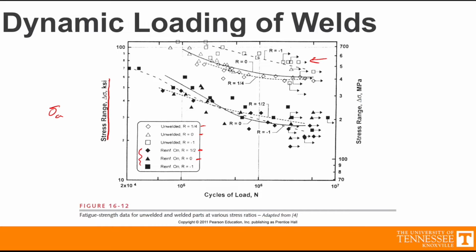One final thing to note about these SN curves and how dynamic loading works in welds is that we don't actually need to worry about correction factors for finding the fatigue strength in welds. And this is because the test data that was collected, so all of the fatigue strengths that are found for materials, have all been found via experimental methods. And so normally when we test an unwelded material, we have a very nice polished little dog bone sample that gets tensile tested or torsion tested or whatever method of testing they're doing. And when we do that, it's a very perfect little specimen.